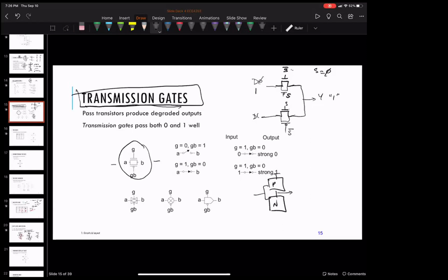Then the next step we took was these complex gates, where instead of having individual gates making a complex logic function, we broke it down and could use a complicated gate to do that function. Furthermore, if we have something like a multiplexer or some circuits like it, we use these transmission gates to make it a more efficient circuit. So these are the exceptions to the pull-down, pull-up network, just for efficiency's sake.